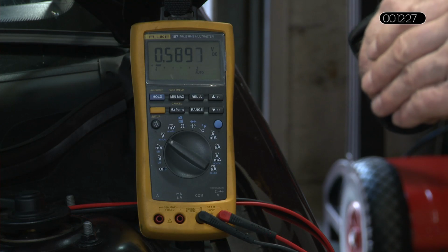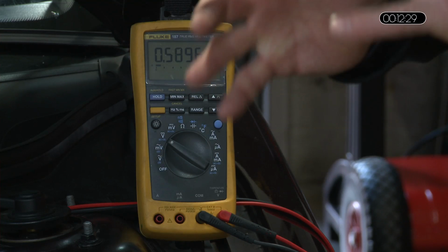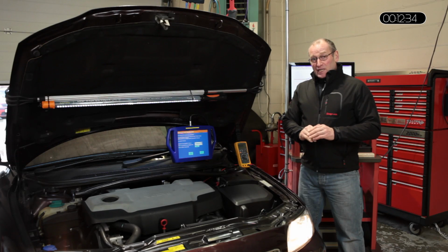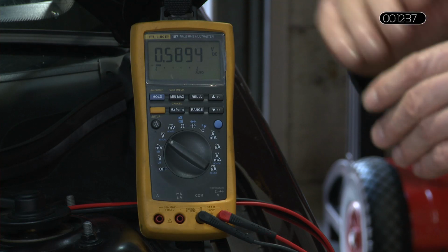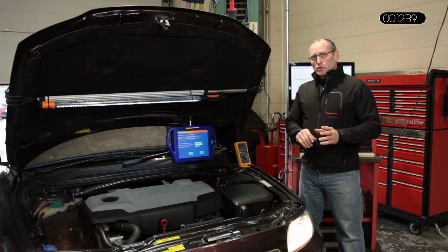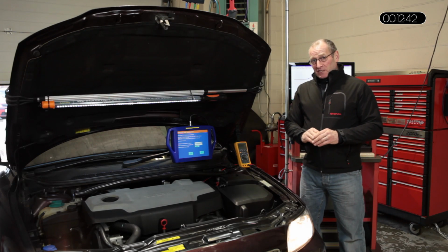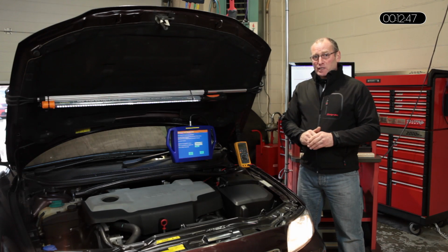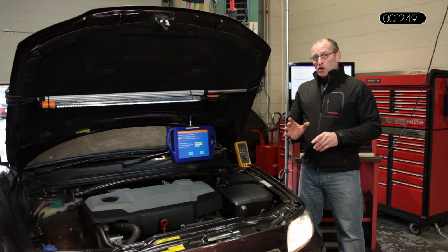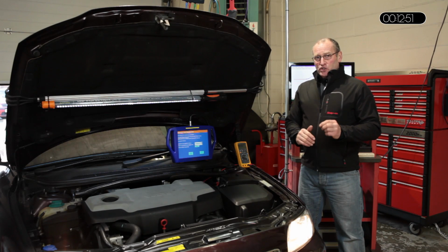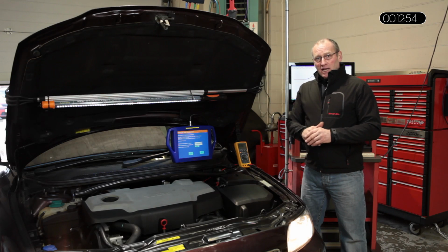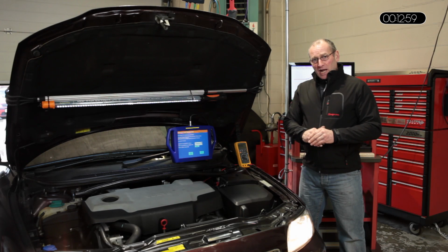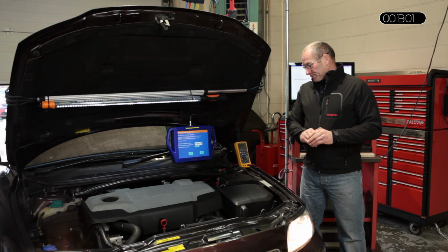However, when we drove the vehicle on the road, this 0.6 of a volt went up to 4.2. Now that's an excessively high figure. The voltage went to 4.2 on full load. Full load, so far as the DPF is concerned, is achieved quite low in the torque range, around 1500 to around 2000 RPM in a low gear. You do not have to drive the engine hard to achieve full gas exit volume. The voltage went to 4.2 and instantly the vehicle went into default.